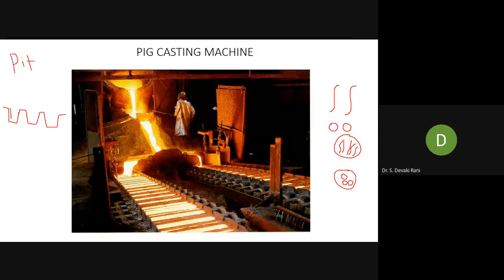So now tell me, what happens here? With dislocations, does strength decrease or increase? If the dislocations are not moving, is the strength more or less? More, ma'am. Ma'am, it results in stacking of the dislocations, which in turn increases the resistance.